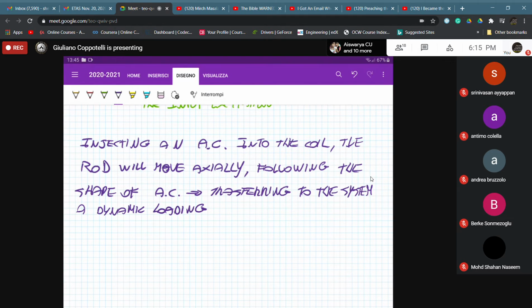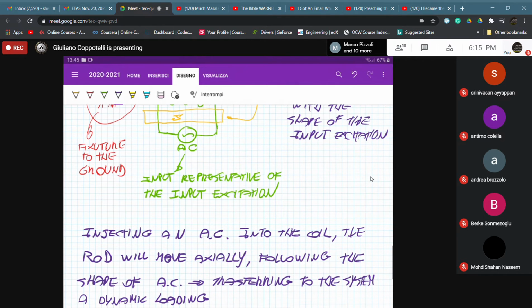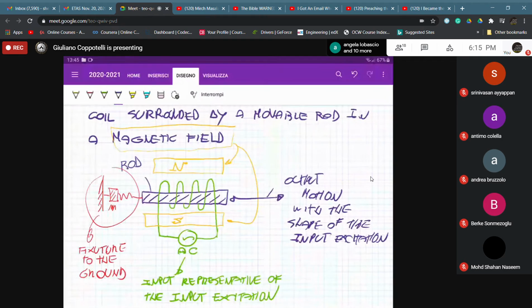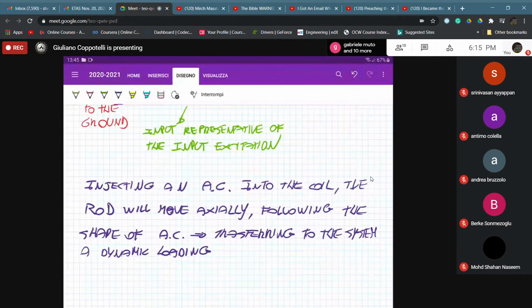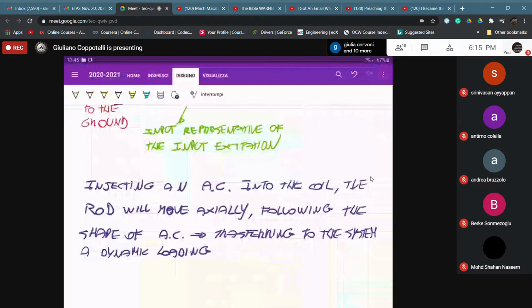Of course we need the required electrical power to correctly excite the structure, and we have to consider the right parameters of this electromagnetic field, that is the number of coils and the values of the permanent magnets, so that we excite the structure with the right response in the frequency range of interest. In structural dynamics, we are mainly considering the frequency range from some hertz up to some kilohertz.